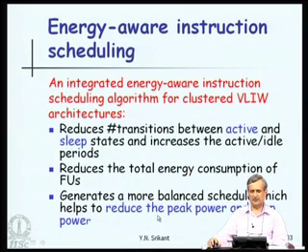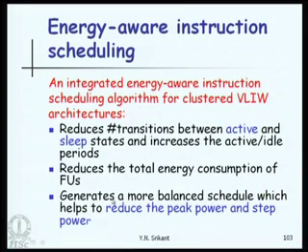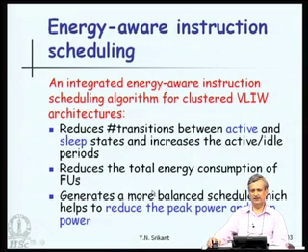So, how is this last point taken care of? The point is if the function units which are busy are kept busier for a longer duration, then there is no need to bring another unit which was sleeping into an active state. If we bring something from active to sleep or sleep to active state, then there is a power requirement. Since we are going to continue using the same function unit, it reduces the peak and step power requirements as well.